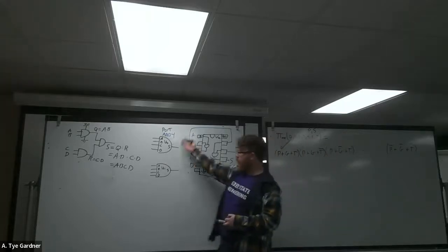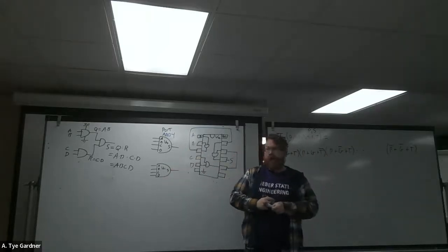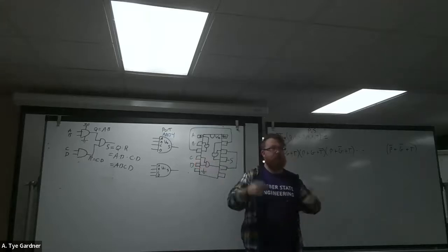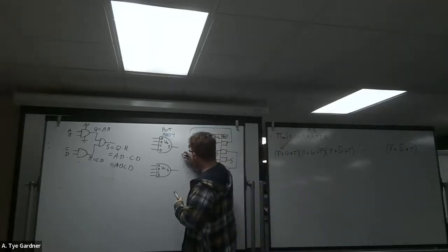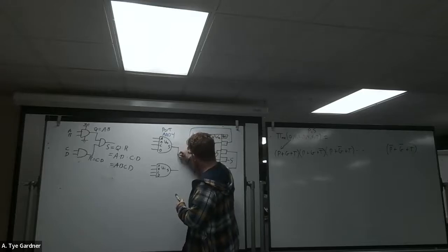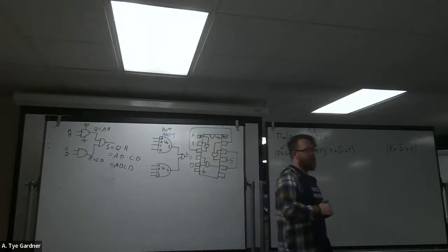So we're going to go from U0 to U, however many of these 4 input AND gates we need. I don't need another one to make an 8 input because I already have 8 inputs. I can call that L for now. The output L, just put it right in the middle of the alphabet.